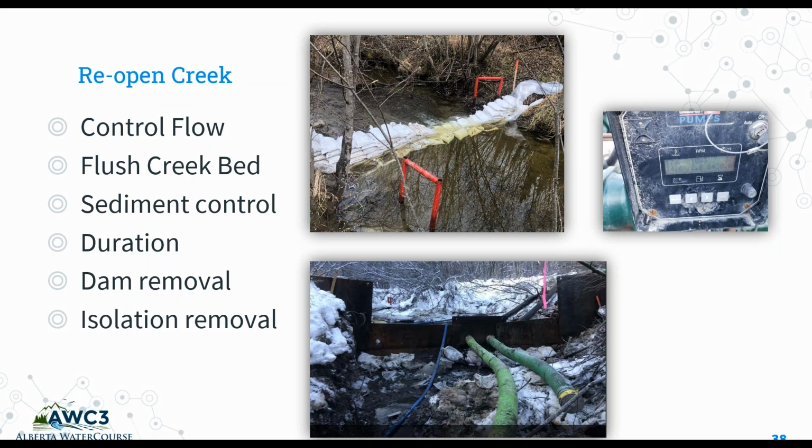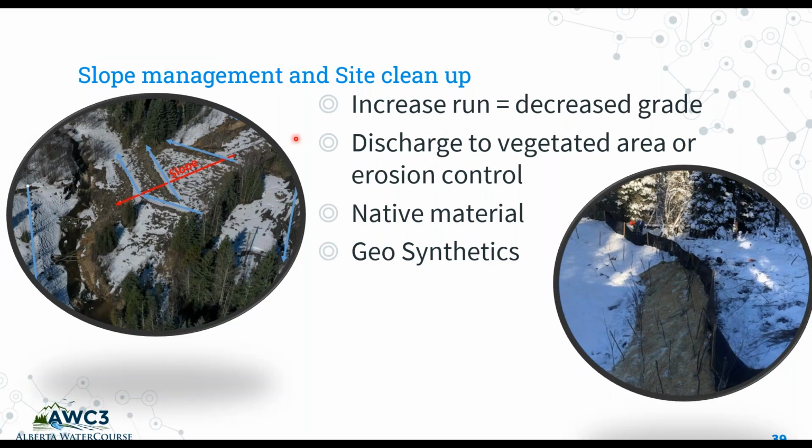Slope management and site cleanup, you'll want to think about if this is your disturbed area and it is a steep slope and it's been freshly disturbed, do you want your water to be running directly down into your excavation?